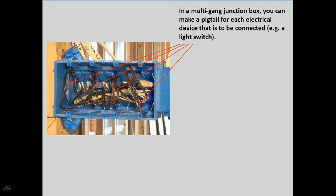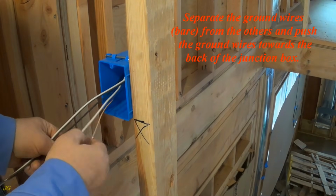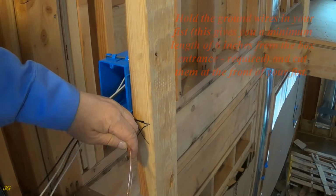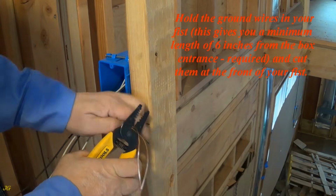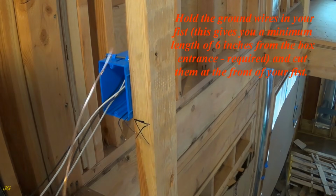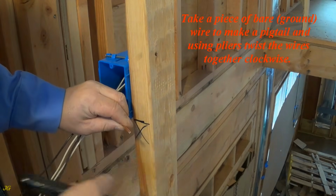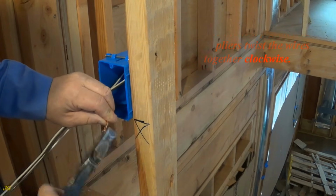In a multi-gang junction box, you can make a pigtail for each electrical device that is to be connected, for example a light switch. Separate the ground wires, bare, from the others and push the ground wires towards the back of the junction box. Hold the ground wires in your fist. This gives you a minimum length of 6 inches from the box entrance, required, and cut them at the front of your fist. Take a piece of bare, ground wire to make a pigtail and using pliers twist the wires together clockwise.